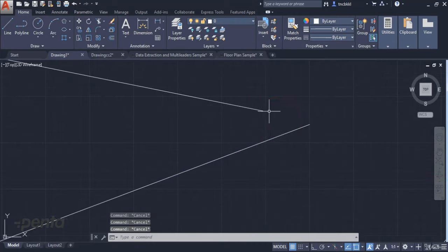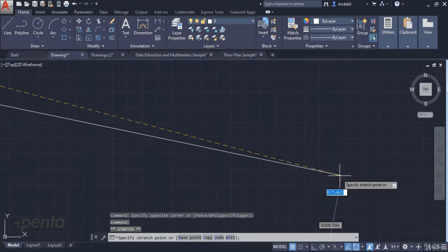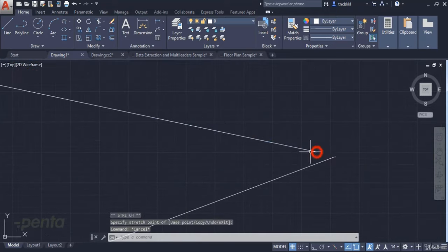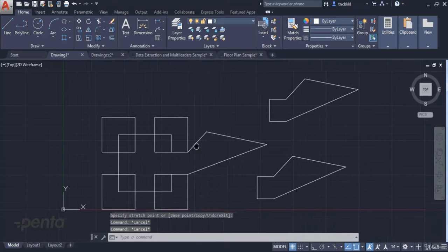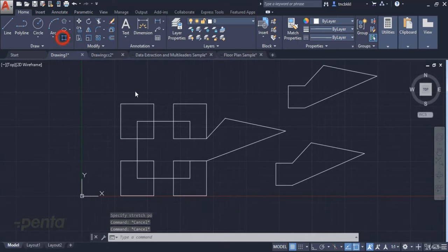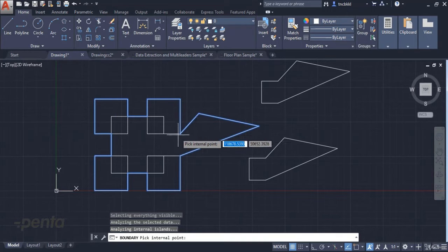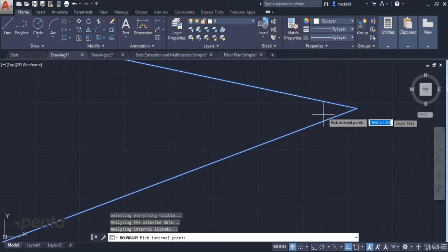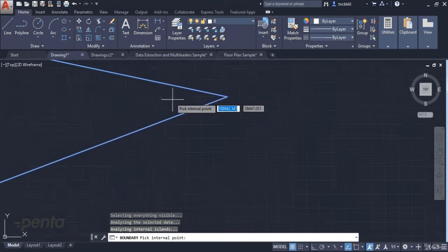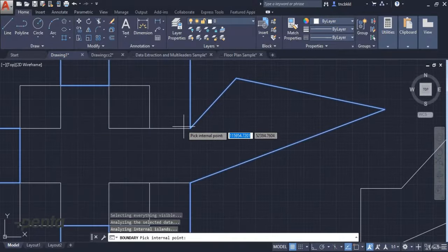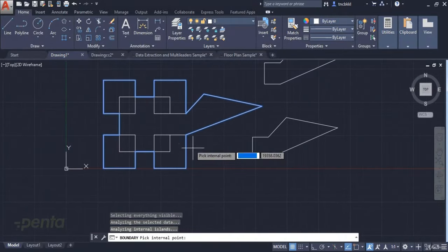Sometimes there might be errors. For example, it might assume that it is very close. Let me show you. We mark the object and zoom in. Let's say that it's here. Now when we look from afar, the edges seem enclosed. Here, we can select pick point and click here. You'll see that it selected a much bigger area because the opening here rendered the function unable to detect the other boundaries and perceived the entire object as an enclosed area, unfortunately.